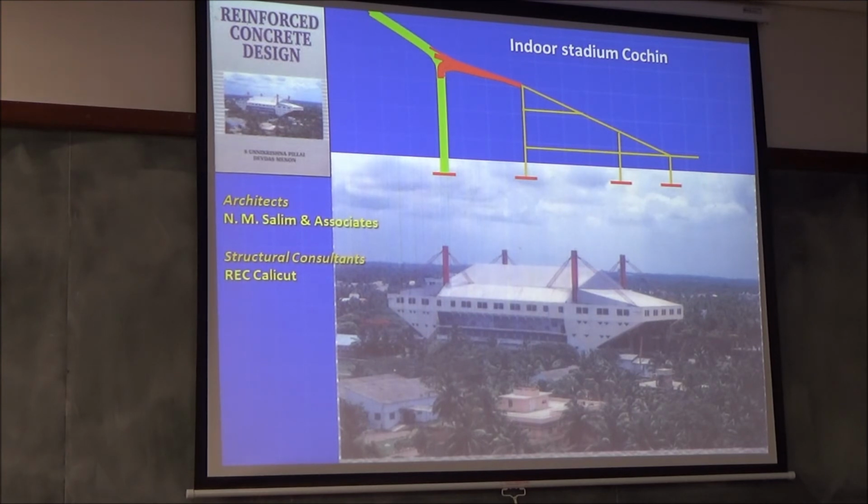Do you know why? Because the cantilever has a back span. And if you don't do it, you don't have proper shear transfer. So unless you give a key here deliberately. So we have to intervene at every stage to make sure, and if you have dynamic loads on this, it can break off. So at every stage you have to be careful of how it's done. The stand sticks out like this at the back, this back side, even this side sticks out.